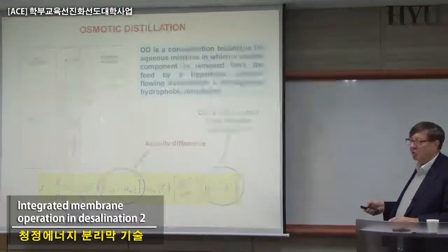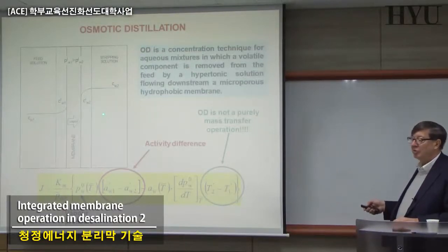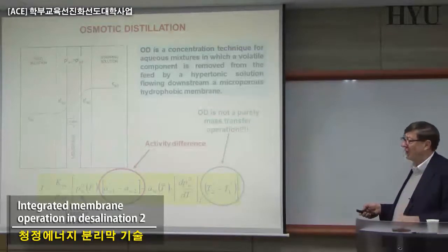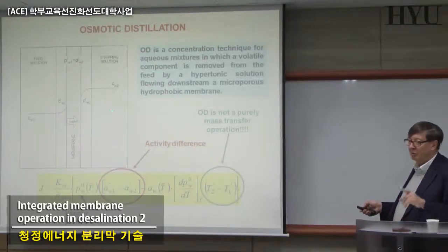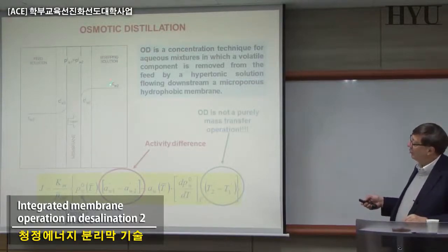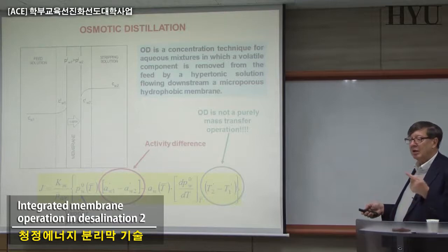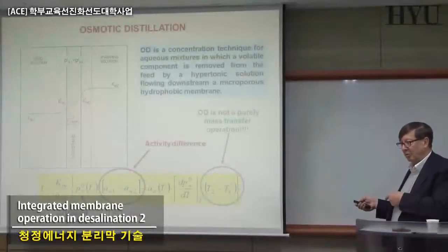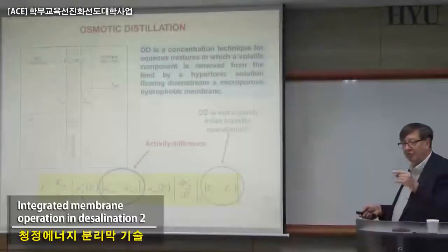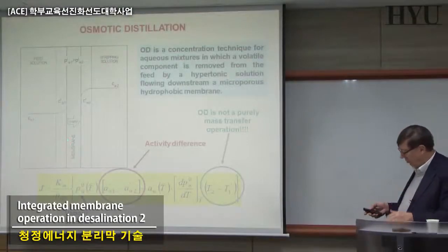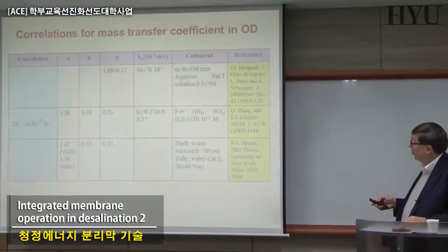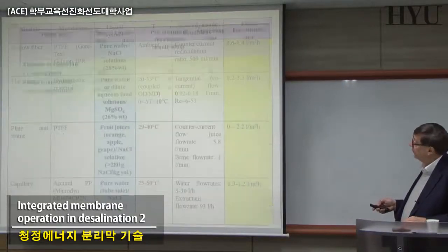Aromas are not soluble at all in a concentrated salt solution. So if you want to minimize loss of aroma, you don't use traditional MD, but use this osmotic approach, where you put here some solution in which the water is soluble, but the aroma is not. And this way you minimize the loss of the aroma across your membranes. So it's a special application, and for people doing this kind of application, you know how to do it.